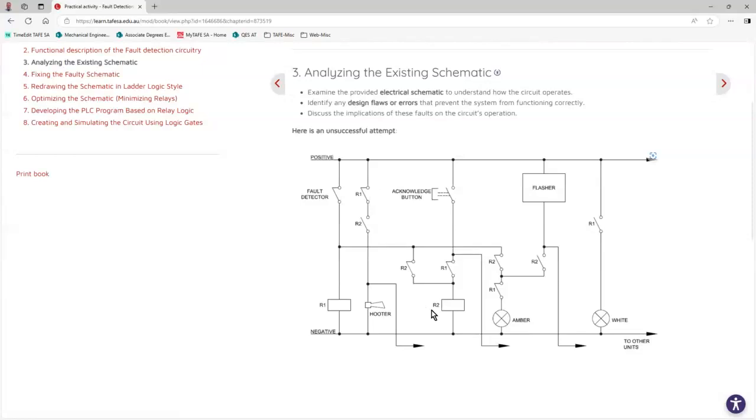What's more, not only doesn't work, but R2, if you turn it on, it'll just burn this relay, because the relay itself will be turning on and off. It's powered, turns on, and by turning itself on, it'll turn itself off, and it'll lose power and gain power, and it'll go into this oscillation mode until it burns out. And all the other functions are not working either, so pretty much that schematic is wrong.